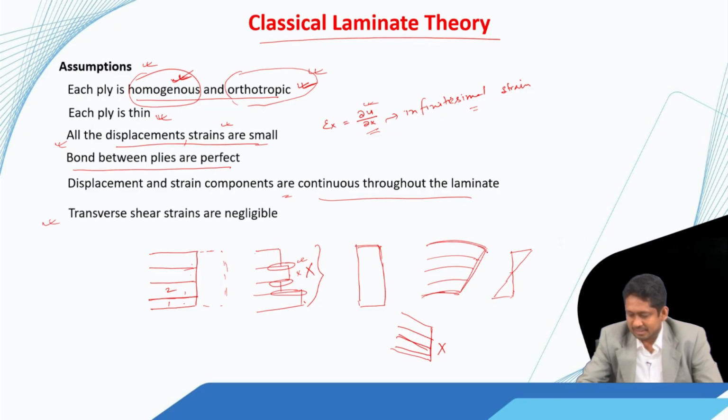And when this happens, at all the cross sections, at this cross section, this cross section, here also, two things happen. First of all, the line which was a straight line before deformation, or if we see this entire plane, this section was a plane section. So, that plane section remains plane before bending and after bending. So, a deformation like this is not possible.